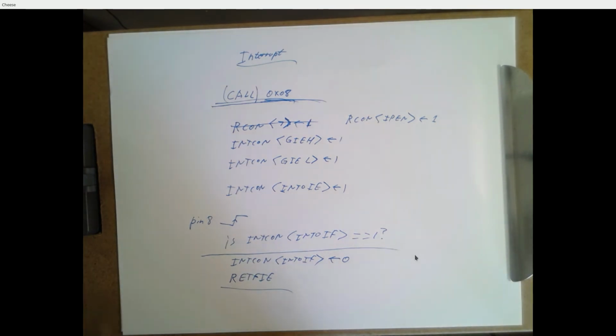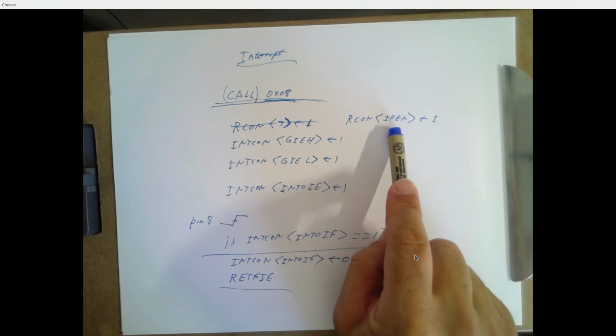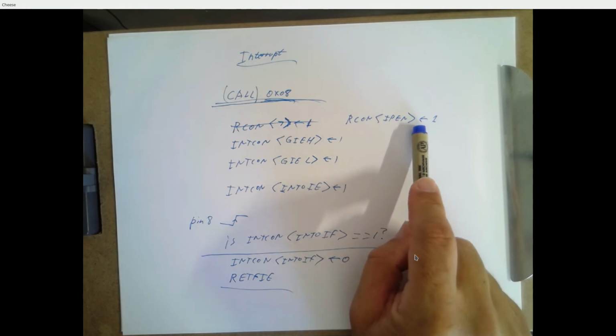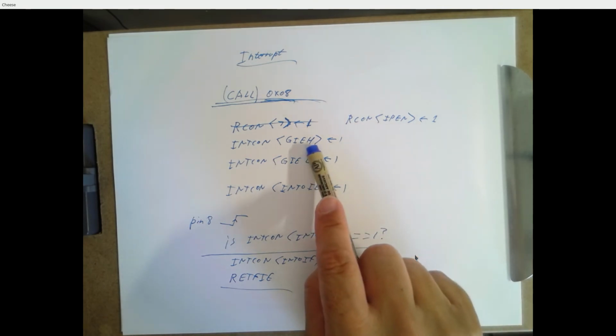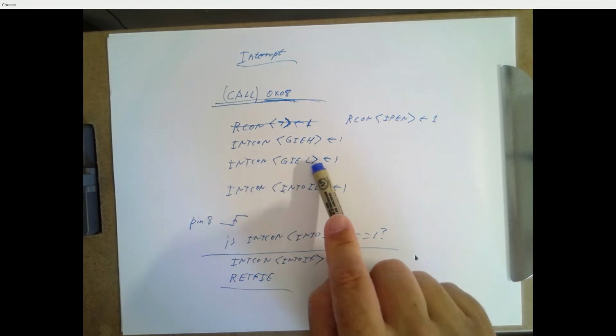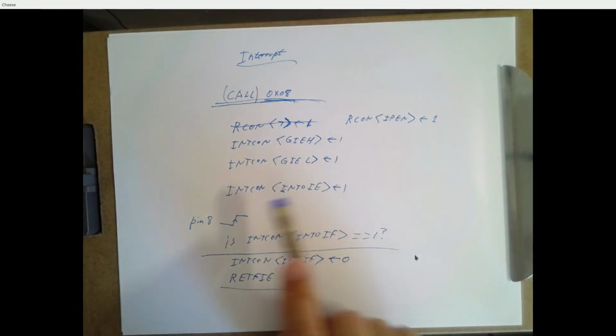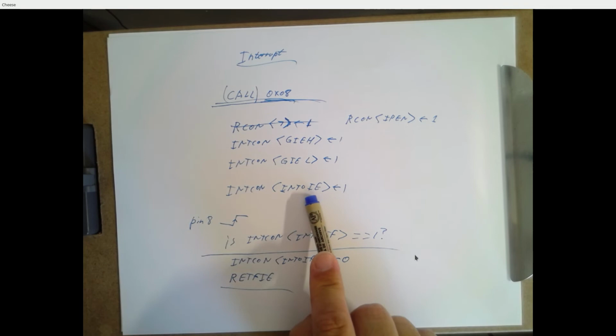All right, so that's the basic setup, and getting comfortable with using these is just something that takes a lot of practice and experience, but the basic mechanism is straightforward, right? So we enable priority levels on interrupts. We always do that. If we want high priority interrupts, we set this to a 1. If we want low priority, we set this to a 1. And then we enable the particular interrupt that we want, int 0 in this case.